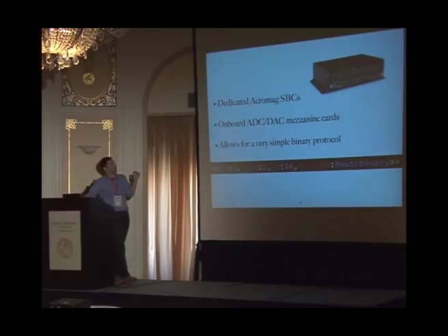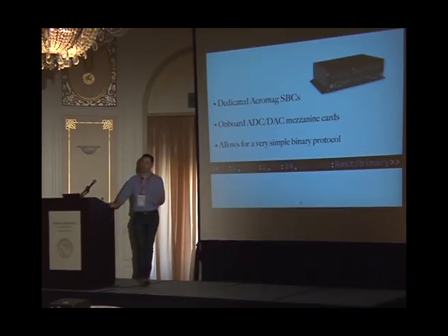This was really nice for us because it lends itself very nicely to a very simple protocol. All you're doing is you're either reading or writing from one of 24 channels on one of 4 cards. So you really only need 2 bits to specify an operation. You need another 2 bits to specify which card. You need basically a 24-bit bit mask to decide which channel you care about. And then there's an optional blob at the end which you may want to use to configure something, set the gain, for example, of a channel. And so that's all contained in that payload.